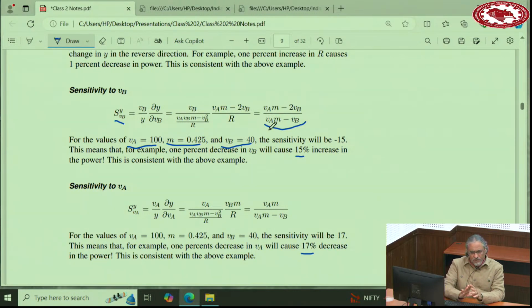And remember, in power electronics, we don't want to insert any resistance in the circuit, so we cannot increase R. Because even if you add a tiny amount of resistor in a 10 kilowatt inverter or converter, you will realize that the power loss will go up significantly. And then you cannot handle dissipating that power loss.